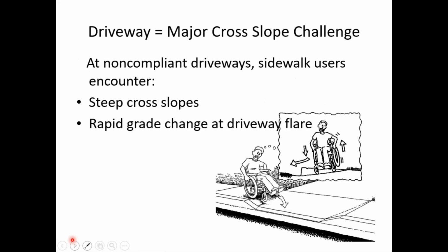Another major cross slope challenge is driveways. Notice here, this sidewalk crosses the driveway. So for the width of the driveway, the cross slope of the sidewalk is the same as the grade of the driveway, which probably exceeds 2%. Also notice the grade breaks, or flares, on each side of the driveway. And I realize this is a cartoon depiction, but it's technically accurate.